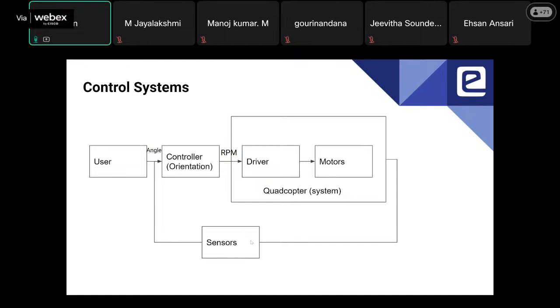Earlier you might have had a doubt, as I haven't specified accelerometer, gyroscope, or the IMU anywhere in the session where we made the quadcopter. So the accelerometer, gyroscope, magnetometer, etc., or barometer for measuring the altitude, all of these are present in the flight controller hardware itself. All those are inbuilt.